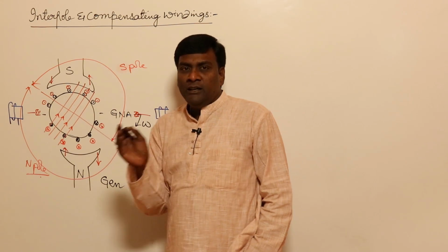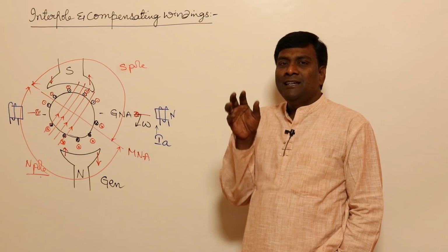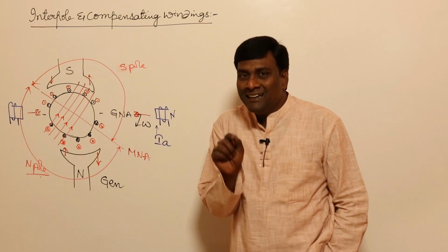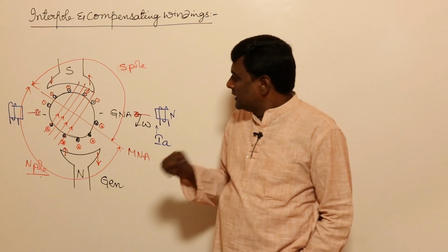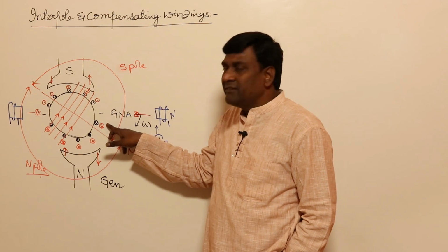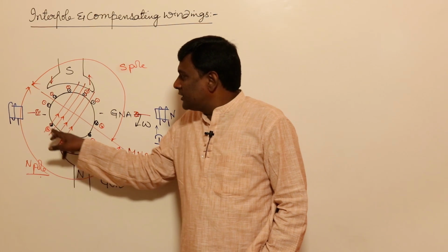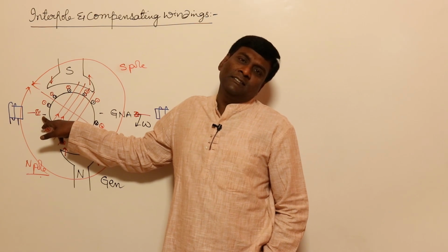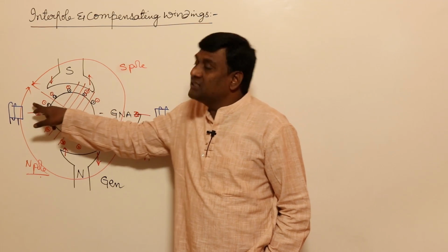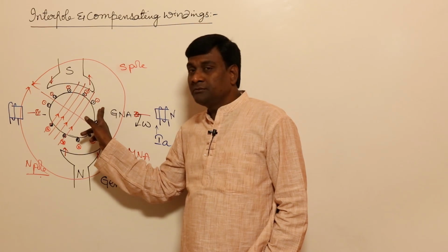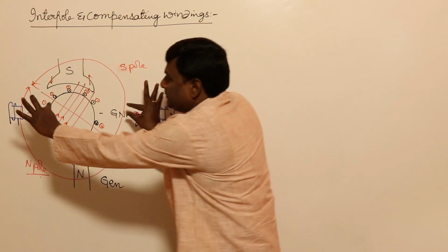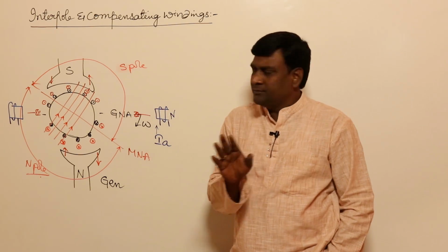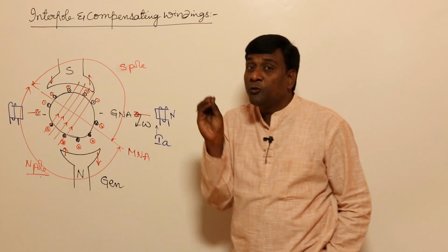I discussed in previous sessions also that armature inductance need not be considered in a DC machine, because my conductor current is trapezoidal. For example, the conductor current here is 5 ampere, the same current, so there will be no change in current, and inductance need not be considered. Then plus 5 to minus 5, stays minus 5, and then minus 5 to plus 5, which means except in the commutating zone, we need not bother about inductance. Anyway, let us think of the commutating zone.